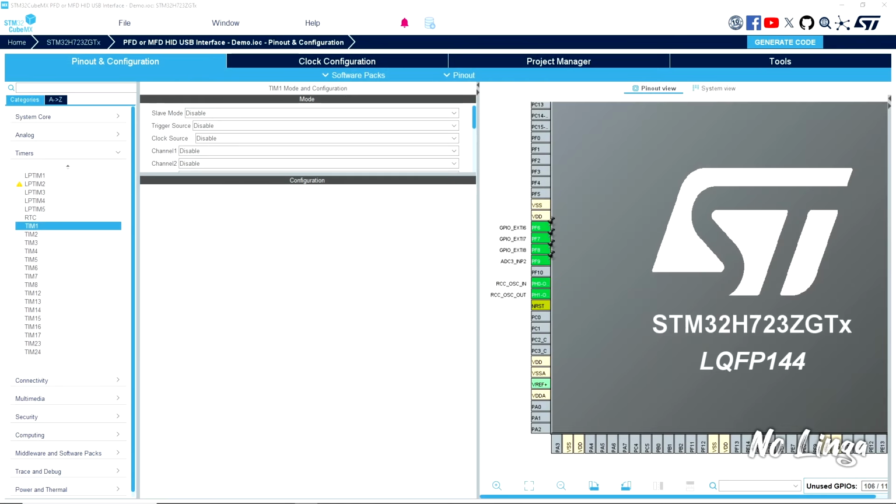We'll start with the encoder configurations. I'll use timer 2 and timer 3 for one of the knobs on my board. With that, that will take care of the knob for channel 1 and 2. There are 2 channels on that encoder. Additionally, there are some other timers you can use here: 3, 4, and 5 are perfect for encoders, timer 8 as well, and timers 23 and 24.